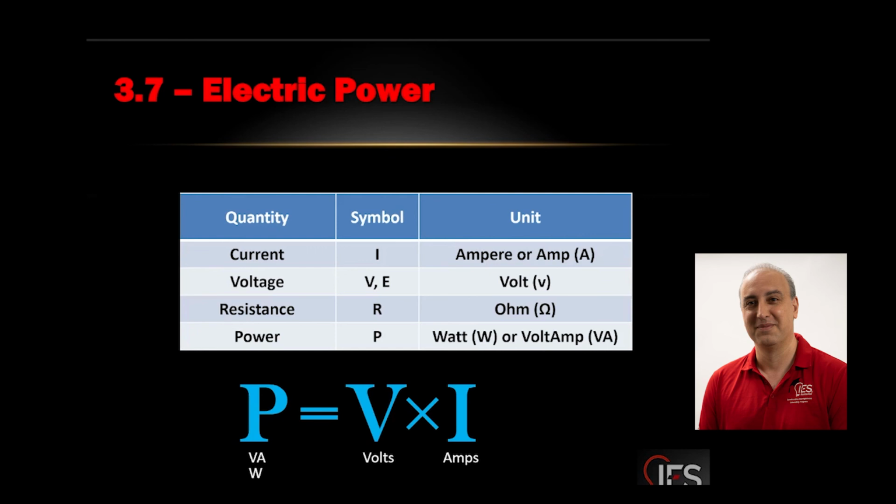There's resistance and capacitance and inductance that we don't want to get into the details of, but the current doesn't flip at exactly the same time. There's a little bit of separation. This one goes first, then this one goes. Then this goes back, then this goes back. The longer that separation gets, the bigger the difference between VA and watts becomes. Because VA is always the same, right? You're multiplying voltage and current. But because of their separation, the true power that you get will be different. So for the wireman test, I want to say maybe journeyman, I'm not sure. You might want to ask George if they ask you about power factor and all that in journeyman if you're taking that test. But for now, we assume they're the same.